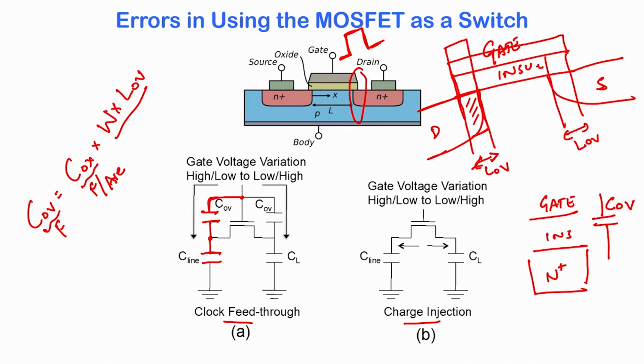Okay. So, if this were your circuit, the switch capacitor circuit that we are looking at, let us say that is the capacitor and we are observing all the voltages on this capacitor, and we saw that there were some blips coming in and going out. So, the circuit that should actually be drawn has this overlap capacitance between the gate and the drain.